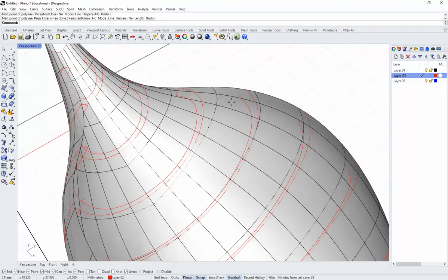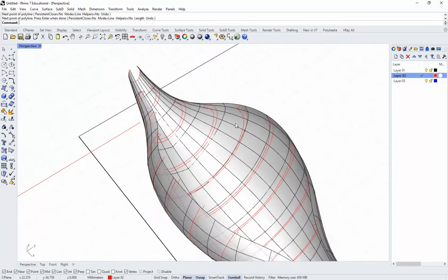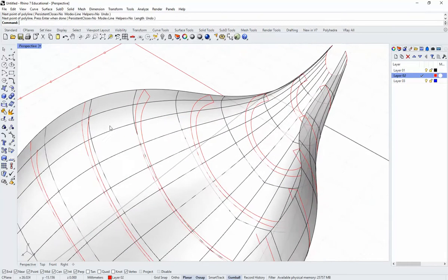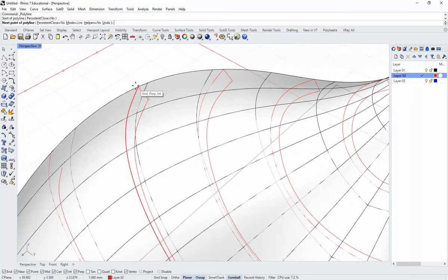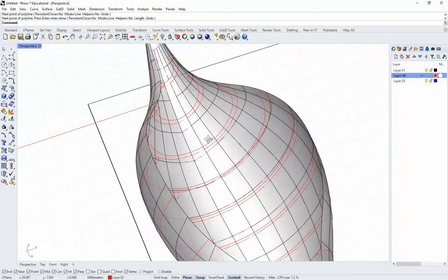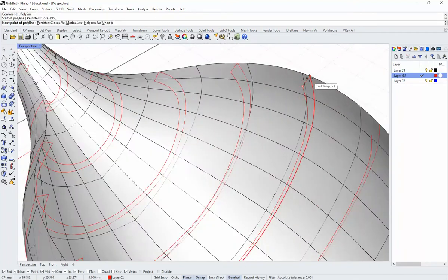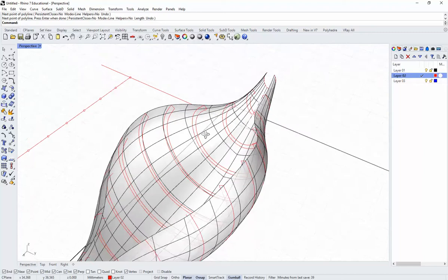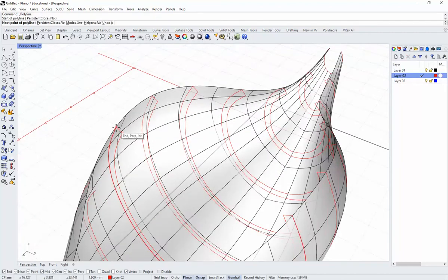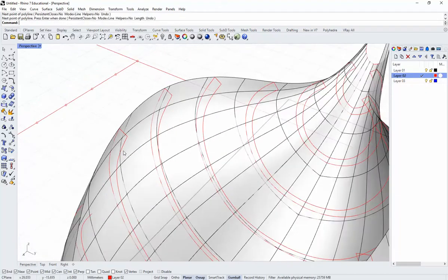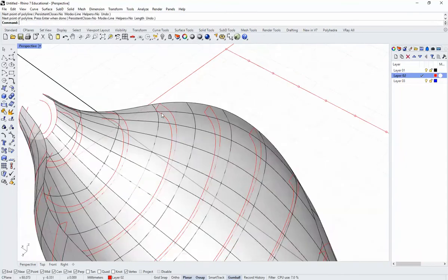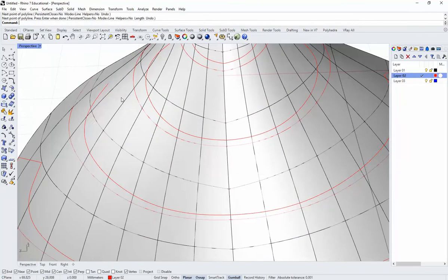You could either start with a lofted surface, or you can follow along with this process, which will actually be to first start with a profile and then extrude that profile, giving it thickness, and then capping that extrusion so that it's modeled as a solid. There's a variety of ways to go about this. If you go with the lofted surface, you can just extrude the surface as well. So it's more or less the same thing. It just gives you a center surface that you'll have to either put on a different layer or delete.